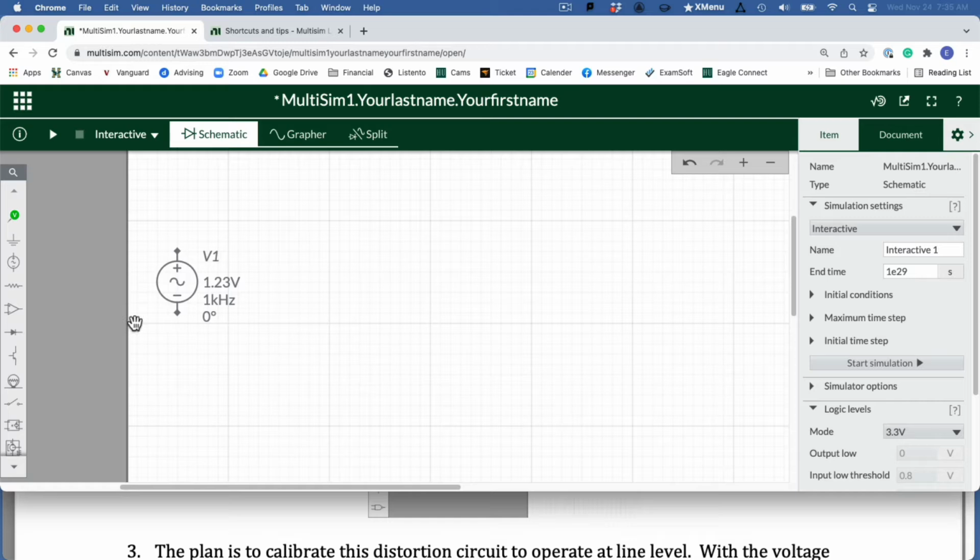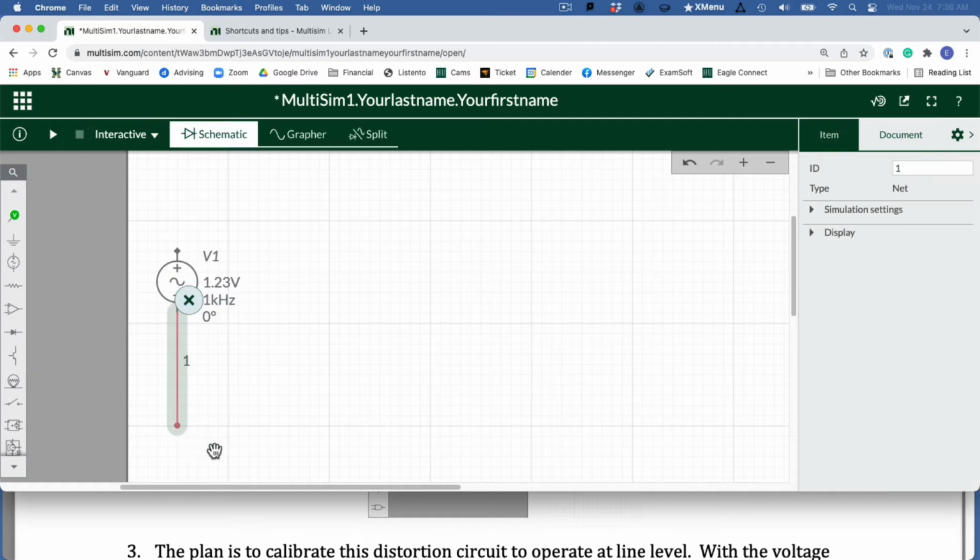Let's connect that to ground, the negative terminal. So let's put a little conductor on it. If I click on the negative terminal and I drag, I'm now making a wire here, and we'll put ground down here. I found that hitting the J key, which makes a junction, is the easiest way to end it. Clicking does end it as well, but I find J easier.